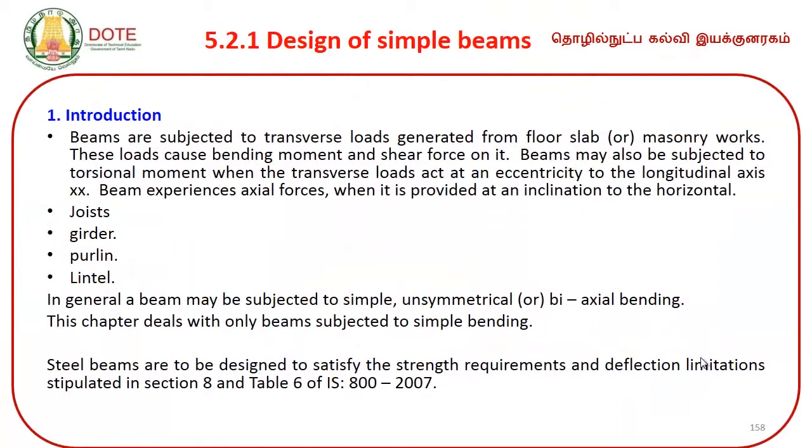Beams are subjected to transverse loads generated from the floor slab or any other masonry works. These loads cause bending moment and shear force on the beams. Beams may also be subjected to torsional moment when the transverse loads act at an eccentricity to the longitudinal axis, and also it experiences axial forces when it is provided at an inclination. So, beams are subjected to shear forces and bending moments, torsional moments and axial forces as the case may be.